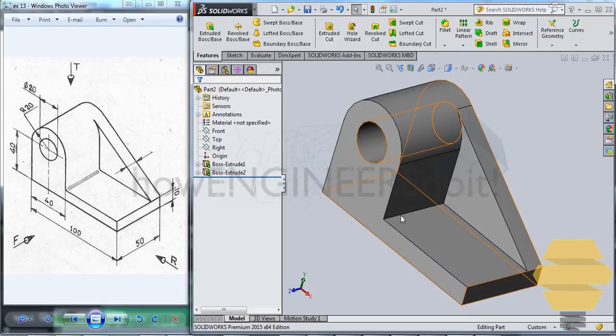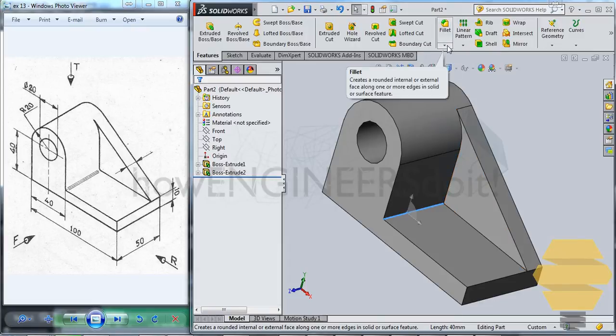So in this video we are also getting to learn how to do the fillet. Just select the edge that you would like to fillet and you will get an option to fillet. Or alternately you can also create the fillet over here. You also have an option to create the chamfer. Maybe sometime in the future when we are doing some exercise, it would definitely come, so I will show the chamfer at that time. For now, it's just a fillet.